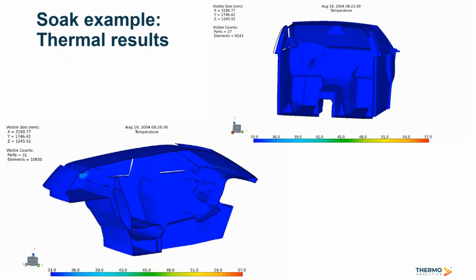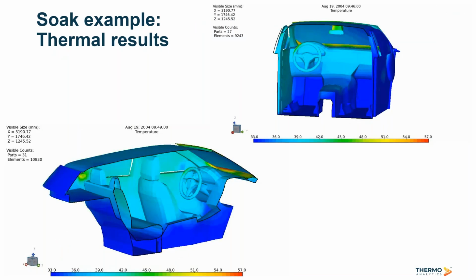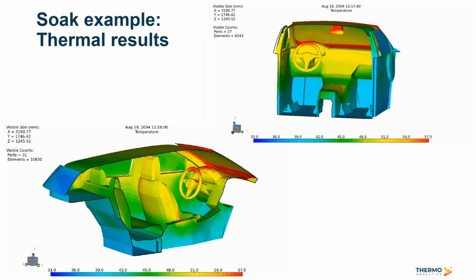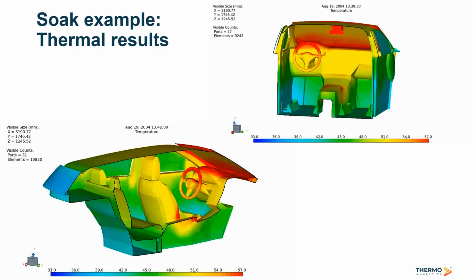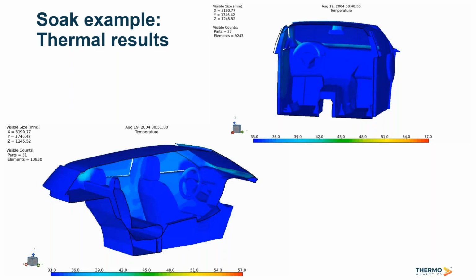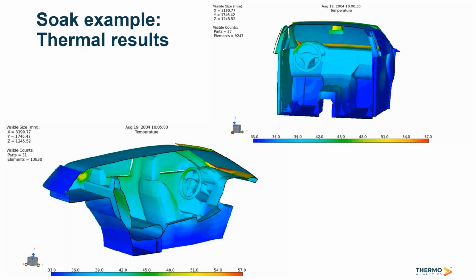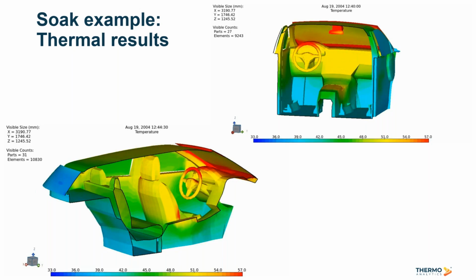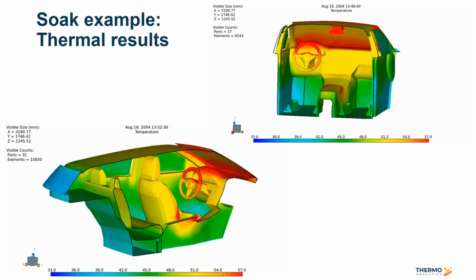So then showing some transient results from the thermal side of things, using those fluid conditions mapped and coupled onto the TAITherm domain and animating the surface temperatures over time through a couple of different cut planes looking at the cabin interior. So again, we can see here how the local peak temperatures are developing, influenced by, again, all the modes of heat transfer.